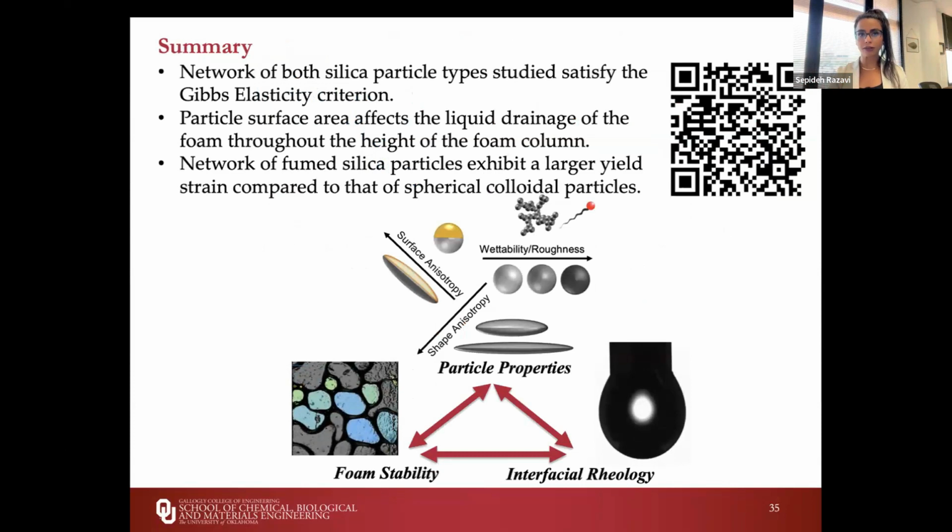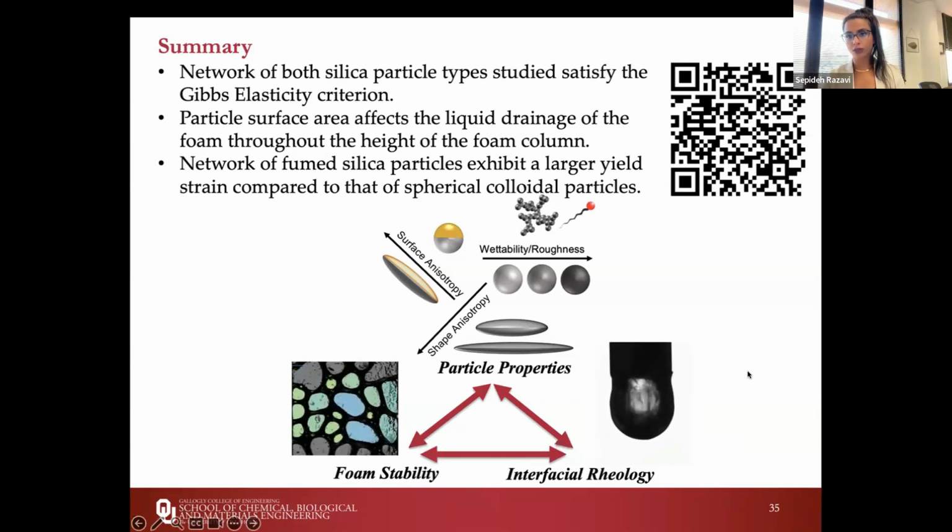Okay, so in summary, I hope I showed you just a little bit of what we do in the space of Pickering foams. In this talk today, I only focused on silica particles, and we showed how the particle wettability is important for trapping them at the interface. But even though we can stabilize foams using particles, each particle and their attributes are going to affect the texture of the foam differently. So there is definitely a correlation between the stability of the foam and also the properties you get at the interfaces using these particles. And these results were published a few months ago. Here's a barcode if you're interested in learning more about the details of this work.